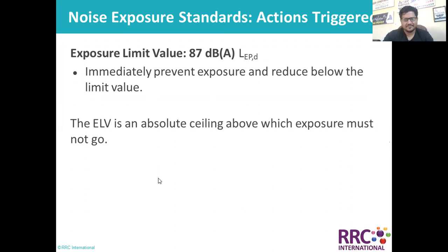So normally in the HVAC room and MCC room, you can find higher noise in that area due to, for example, HVAC, generators, the chiller and so on. But sometimes in the plant itself, nearby blowers, pumps and so on, you will find high noise sources. So as an immediate action, if we find something more than 85 decibel, we are going to do painting on the ground and erect safety signages, which mention after the study whether single hearing protection or double hearing protection is required.